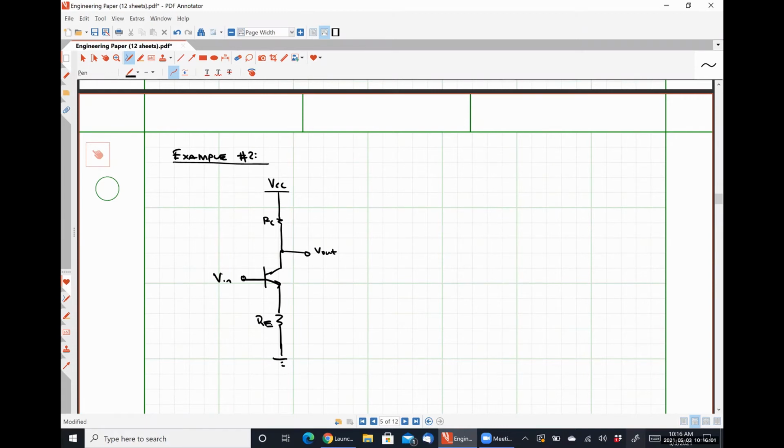So I would argue that based on the behavior of this circuit, a common emitter amplifier that features emitter degeneration behaves like a negative feedback amplifier, okay? Now, you may look incredulous, and that seems perfectly reasonable to me, because if you asked me where to define the feedback loop for this, I couldn't do it. I literally tried this morning to work it out mathematically so that we could break the circuit and all this kind of stuff, and could not get the results that I want. But its behavior exactly follows that of a negative feedback amplifier.